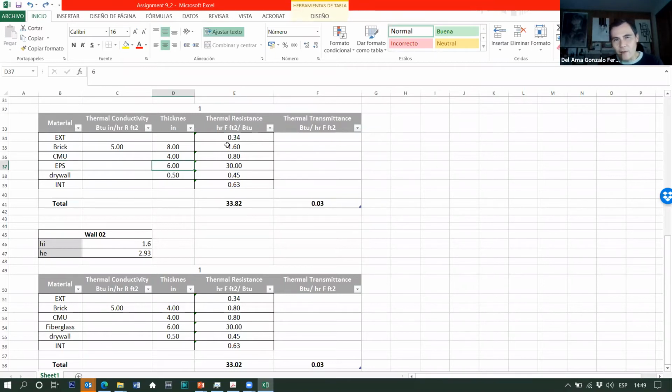You remember that the R value of thermal insulation was 5. The thickness was 6, so 6 times 5 equals 30. So imagine that you double the thermal insulation. That would be 12 inches, so that will be 60, because it would be 12 times 5. And now this total value is 63. It's above 50.